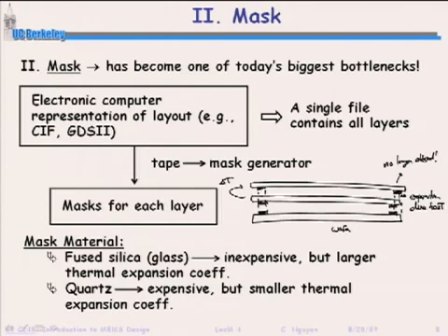So how do you solve this problem? Well, it turns out the way to solve this problem is that you do not allow your mask to align this feature and that feature on 2 sides of your wafer. You never allow your mask to do that. In order to get the best resolution, you have to use what's called a stepper, a reduction stepper, and we'll talk about that in a few minutes. But first of all, that was the difference between these two materials. You like quartz. If you need very good resolution, very good alignment, you need quartz to do that.